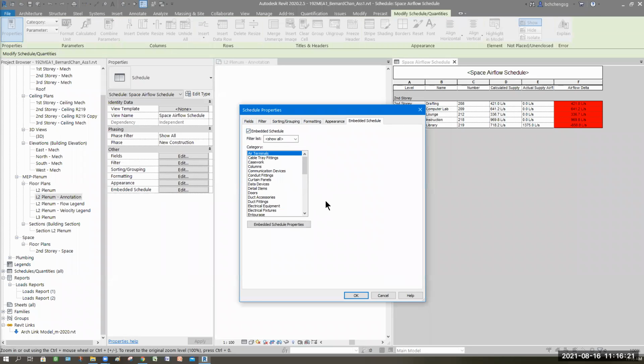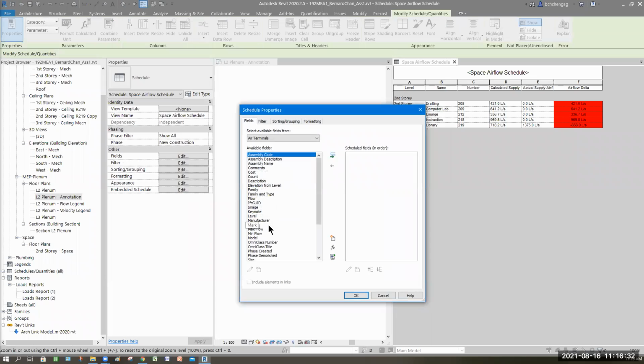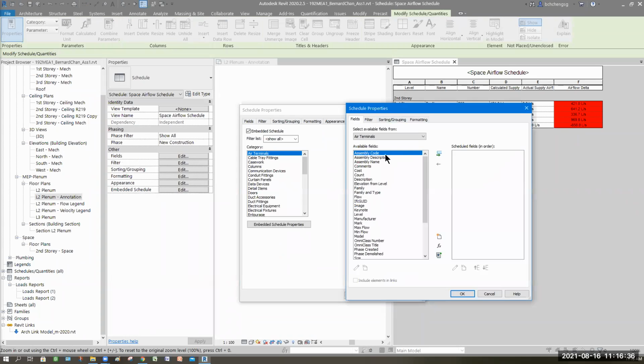After that, see what information is required. So they want us to select the air terminal, which is there. So enable properties. All right, you can see what they want us to add. Air terminal, right? Correct. Then the field we want is system type. So system type is here.